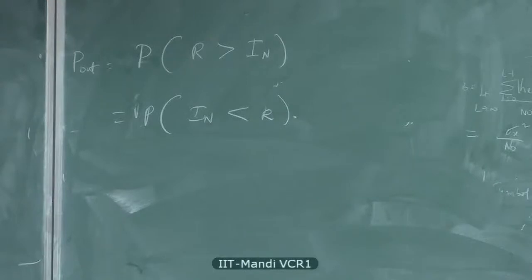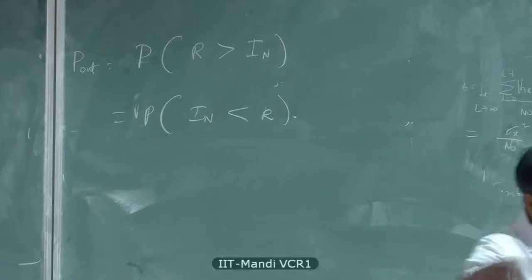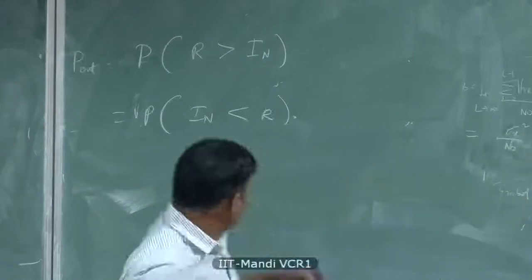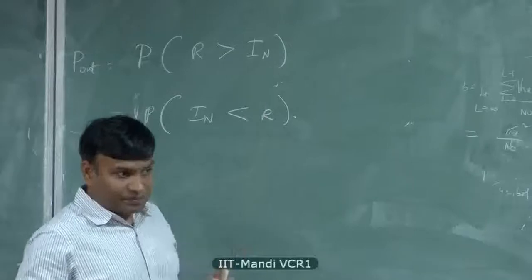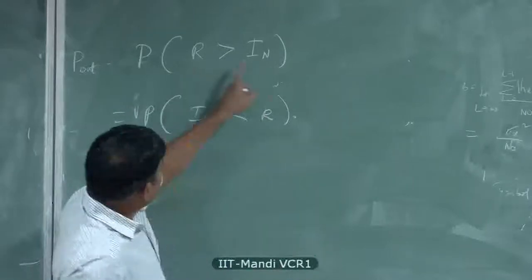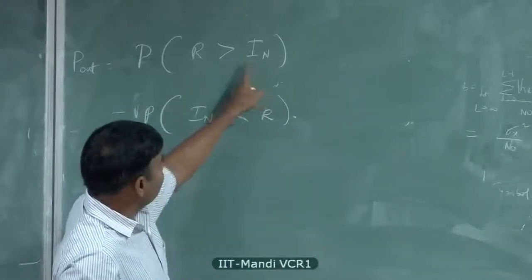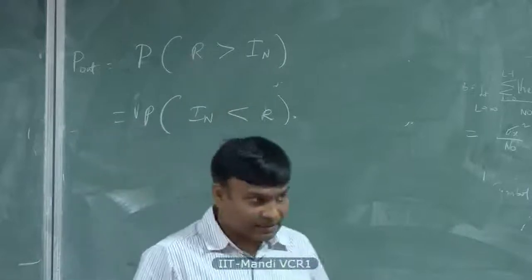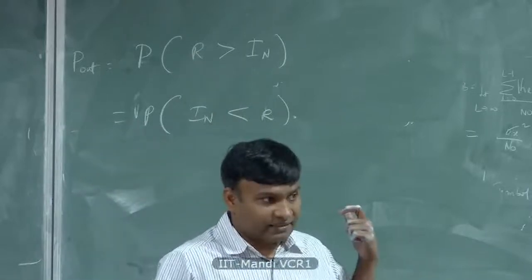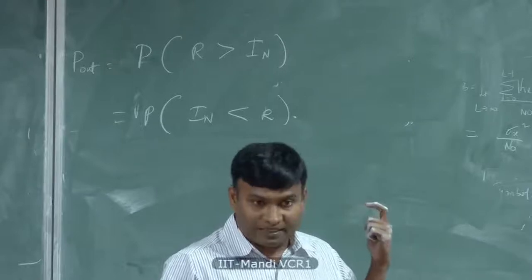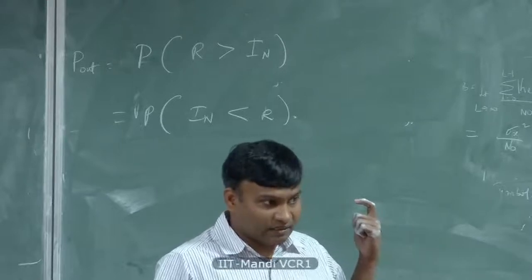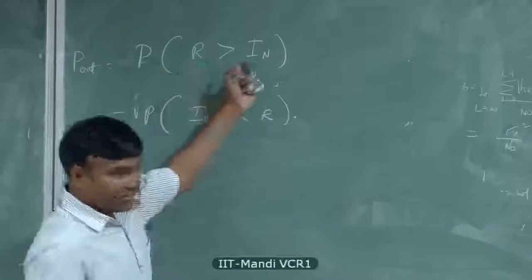Okay. Unfortunately, In is a function of the channel, and the channel changes from time to time. Right? But the variation is, well, the channel changes from one time epoch to another. Okay, but you fix this rate R. Every time the mutual information falls below R, an outage occurs, and you want to calculate this rate, right? How many times does it happen? That is the probability, right, of occurrence of this event.